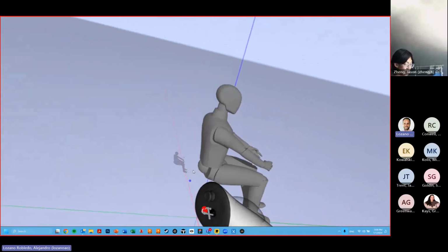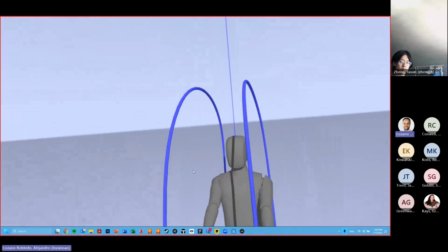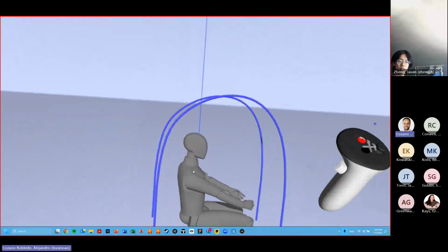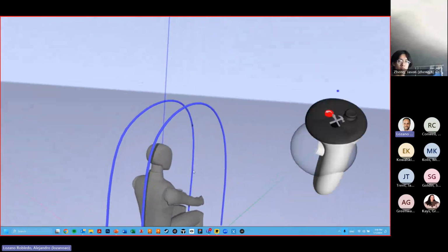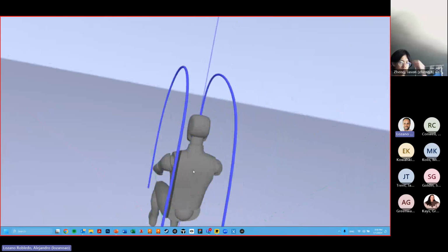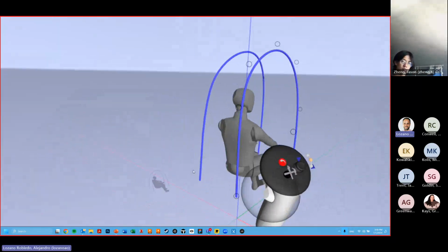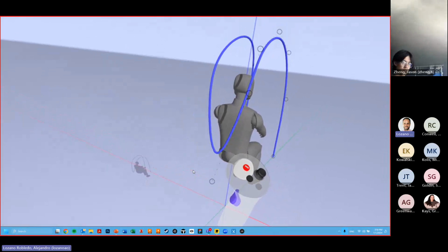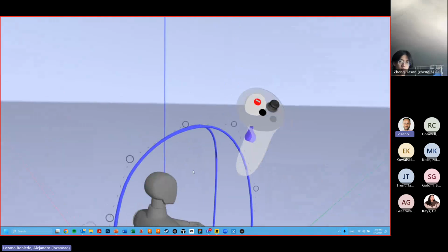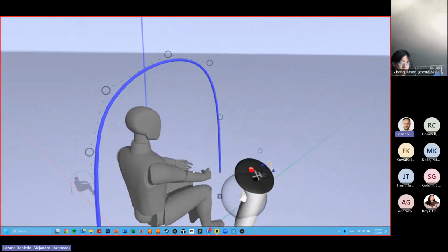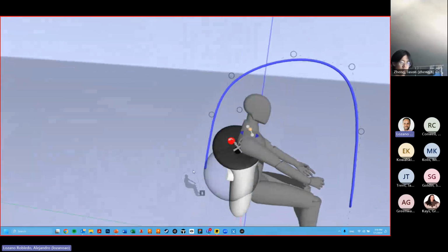What I recommend is start simple. So start with a few points. Let's say I'm creating a canopy for this person's car. This is not very accurate, right? This is just very all over the place. How Gravity Sketch works is you just need to drop something simple, and then you can go into the edit mode of the points and start modifying. So look at how, if I bring these points close to the center, it basically snaps them at the center line, which could be pretty helpful. So now I have pretty much a really nice center line sketch.